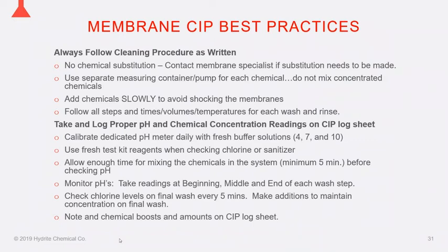If the chlorine falls off quickly, even after numerous additions, it may indicate that you still have a significant amount of protein or soil in your system. You may need to do an additional wash.